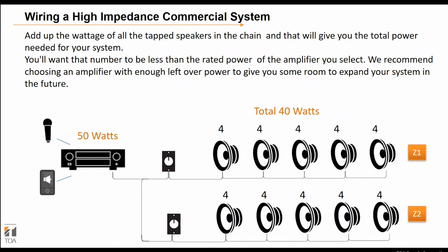So you always want to have at least 20% of headroom as a general rule on any system, whether that's low impedance or high impedance, to give yourself the extra headroom for either expansion on a 70 volt system, or to handle those peaks and valleys that we see with a typical audio signal.